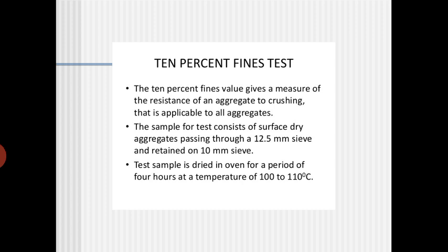If 10% fines are produced, then note down that compressive load, that is, for 10% fines how much compressive load we are going to get. That can be calculated.